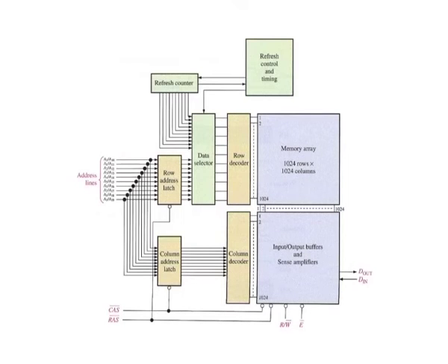The 10 address lines are time multiplexed at the beginning of a memory cycle by the row address select and the column address select into two separate 10-bit address fields. First, the 10-bit row address is latched into the row address latch.